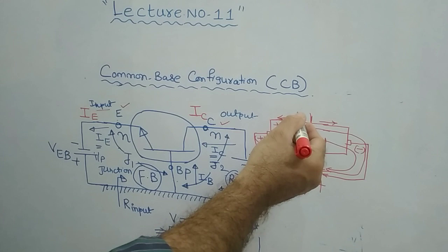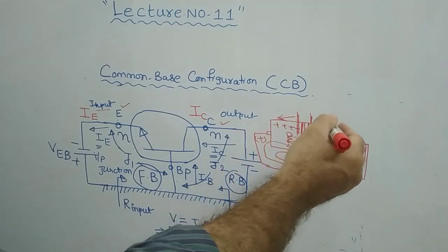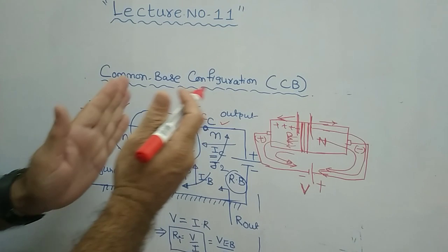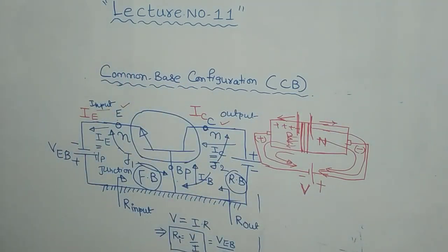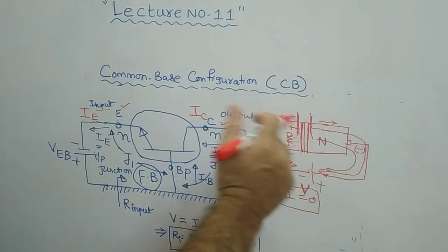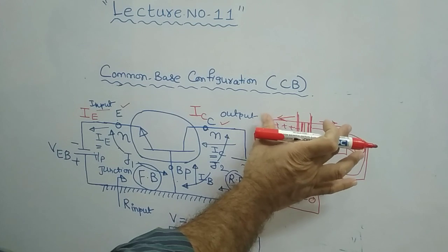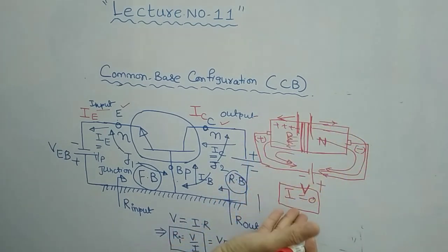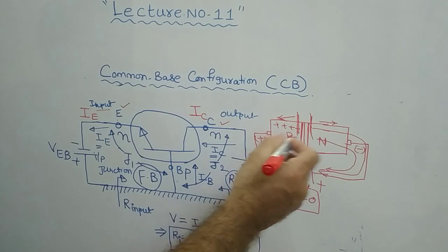This is the junction. The holes come in this way and the electrons go in this way, and they go away from the junction. There is no recombination here. Clear? Therefore there is no conduction in reverse bias. That's why we can simply say that the current is zero in reverse bias condition, because electrons and holes are not combining with each other. As there is no conduction process, the current due to majority carriers is zero.